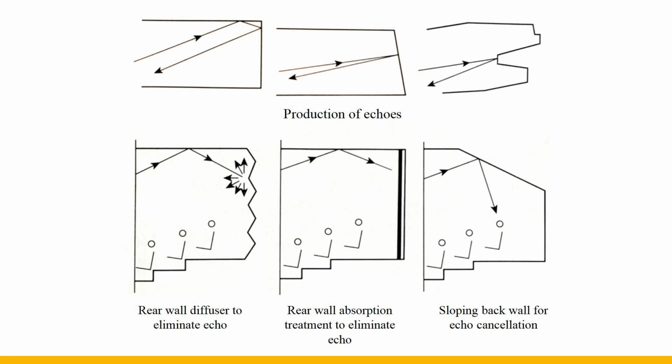The position of the sound source is set in various possible positions, and the situation of the speaker as the sound source should also be considered for the electroacoustic sound. The reception point should not only consider the auditorium, but also the stage. The above picture shows the places most prone to echoes, namely the back wall, the ceiling near the back wall, and the front of the ceiling at the sector. Rear walls with concave curved surfaces should be avoided as much as possible because acoustic focusing will enhance the intensity of echoes.